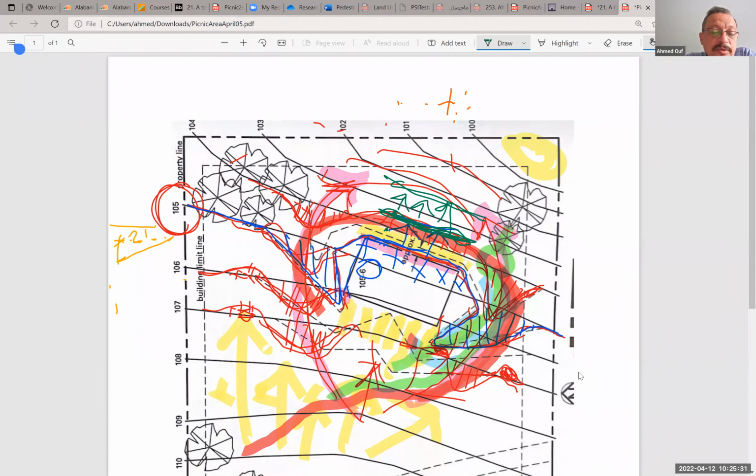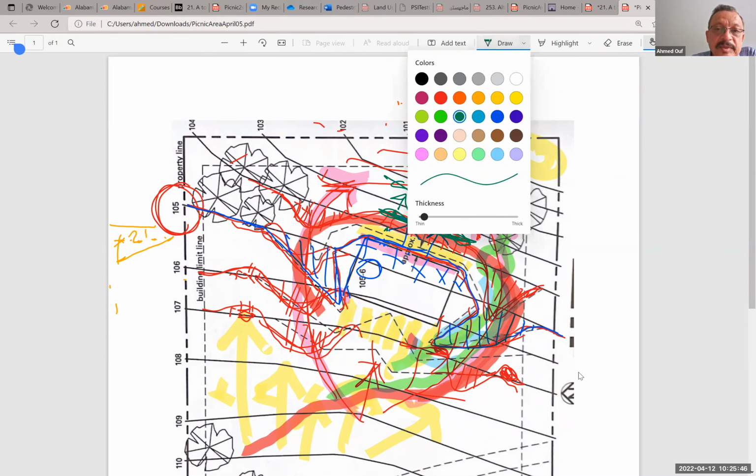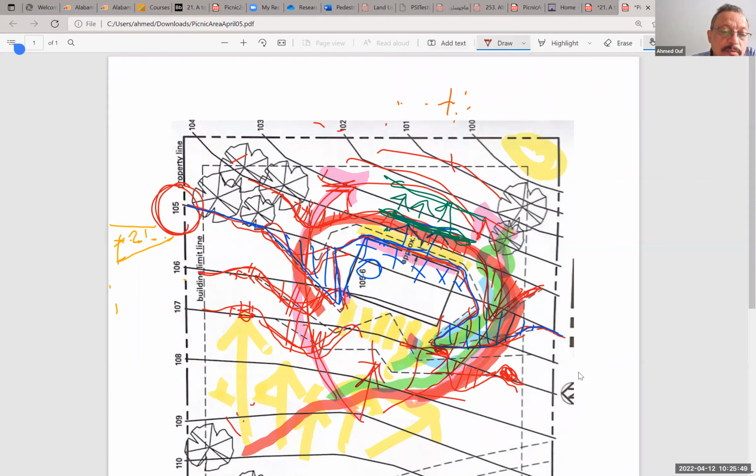I would like you to make the same exercise that we have here, which is creating a pedestrian path of, say, 1 to 20 to make sure that we don't need a handrail for the slope of this. And hopefully we don't need that in here, but if we need something up to 1 to 12, then we will need a handrail in this area and maybe a handrail in this area here, but make it very small.